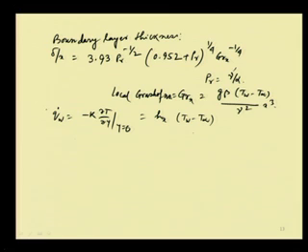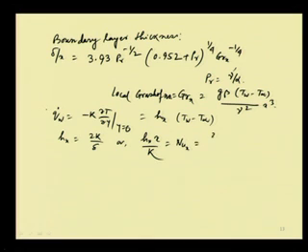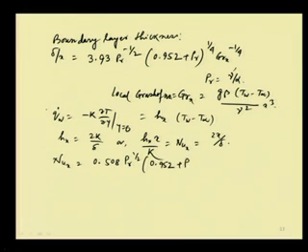From there, by putting the value of del T by del y at y equal to 0 from the temperature expression, we find hx is equal to 2k by delta. So hx x by k, which is the local Nusselt number, is equal to 2x by delta. So the local Nusselt number is given as 0.508 Prandtl to the power half into (0.952 plus Prandtl) whole to the power minus 1 by 4 into Grashof x to the power 1 by 4.